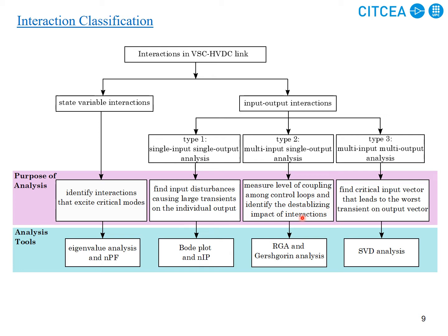If I have a strong coupling between two variables, two control loops, then I need to take measures to reduce that interaction. Or on the positive side, if the interaction is high, then I can make a feed forward between these two control loops and counter the deteriorating dynamics of these variables with different approaches. One of them is loop decoupling. The other one is the concept of feed forward to decouple the dynamics.